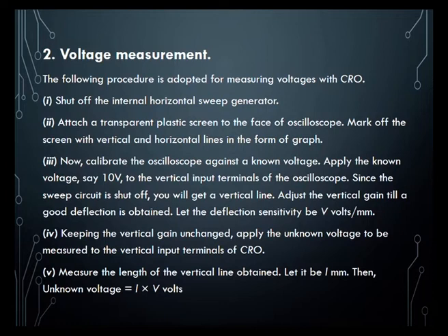Here, V volts is initially the known voltage, 10 volts, and L is the length of the vertical line observed on the screen, which we measure in order to find the unknown voltage.